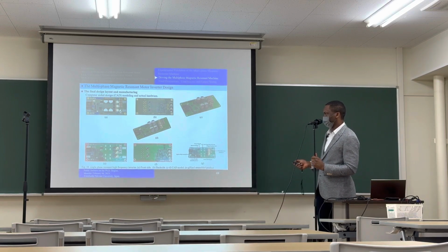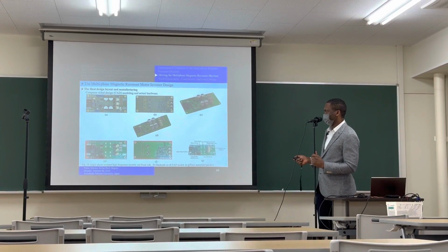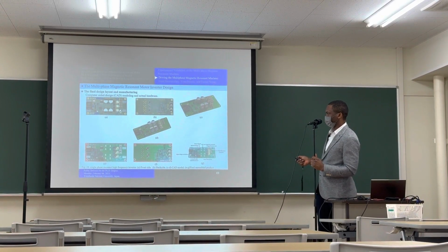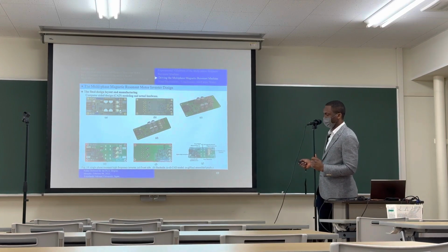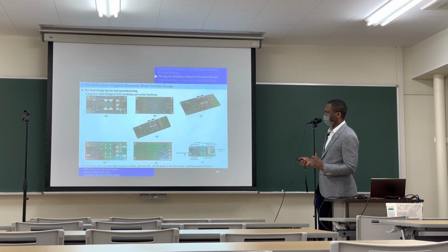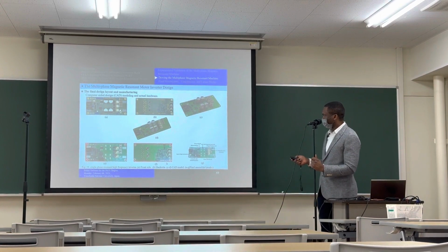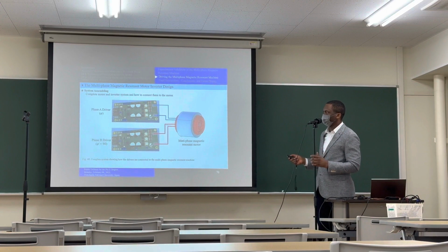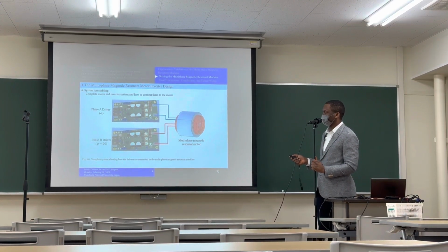And for the board, we have the main power MOSFET with the amplifier. We have the sections that we are going to connect to the main machine. We have some sections to measure. And then we have a resonance capacitor that we added for 200 kilohertz. And then the input voltage. But the idea, of course, like I indicated before, is that we need two of these. We need two of these drivers to run the motor.